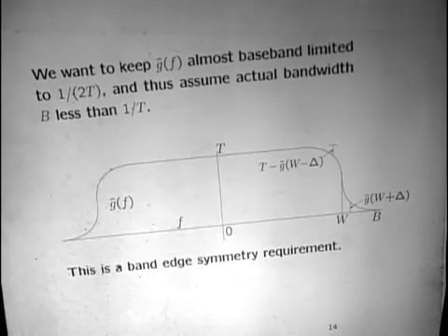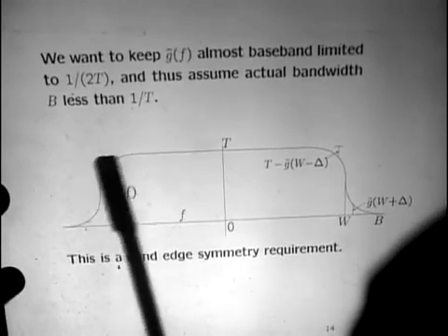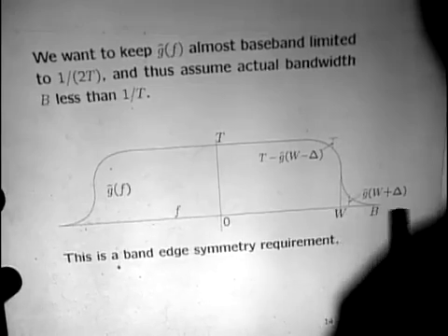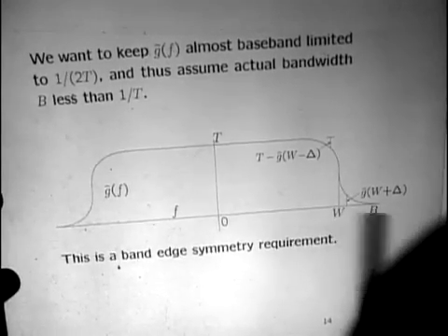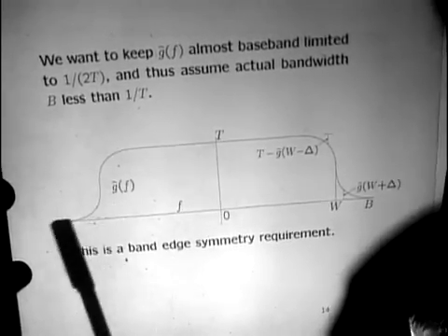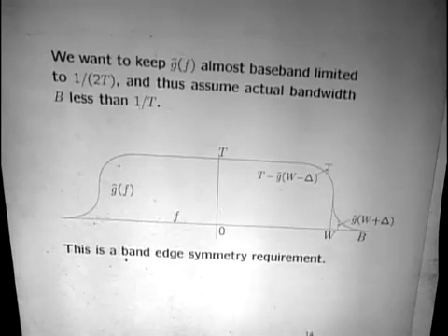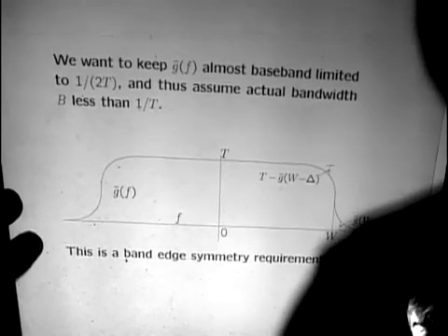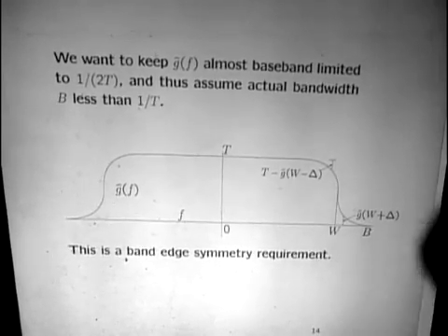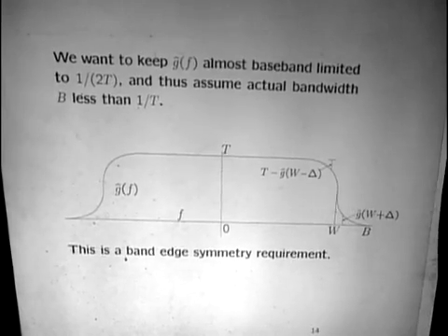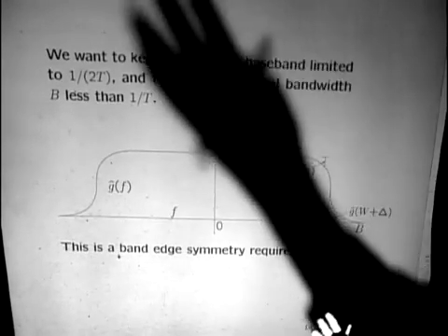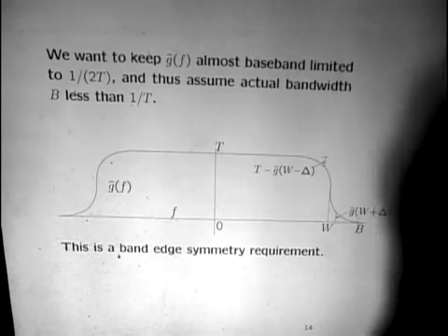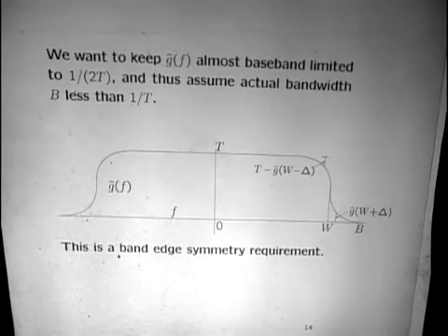If you were using the sinc function, what you would get is something which is a rectangle here, cut off right at this point, and cut off right at this point. Nyquist is saying, okay, well, suppose it's limited to at most 2W. In other words, suppose you have a slop over into other frequencies, but at most into the next frequency band, and no more than that.